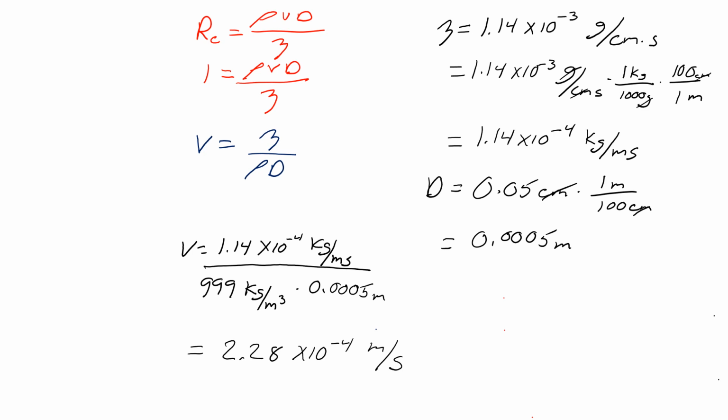So in most Darcy equations that you use, and we'll do some later in the semester, at the end of using Darcy's law, you always have to go back and make sure that Darcy's law was valid for that problem. You need to go through and calculate the Reynolds number to make sure the water wasn't moving too fast and not violating the mathematics of Darcy's law.